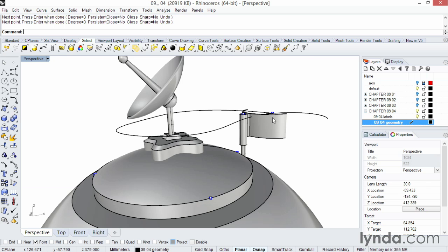More often, you might find it easier to draw or build geometry directly on the construction plane, where you have more control and you can use the grid. Then move your finished geometry later to its final location. Optionally, if you're doing extensive work in a different location, you could then move the construction plane to the level it's needed and avoid using planar altogether.